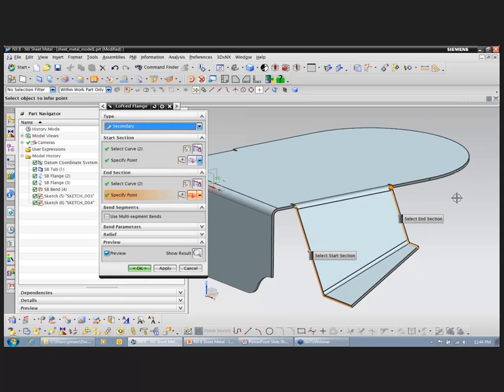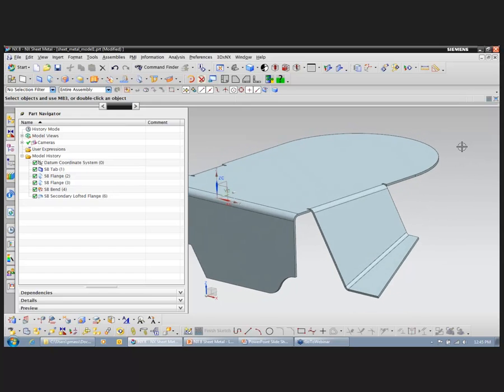In regular modeling space, this would take much more effort to produce a similar result. It's a powerful tool, this sheet metal application. I really like it. I wish it would have been around back when I was in configs design in the aerospace industry. That's what I did day in, day out, was create sheet metal brackets and tubing that run on the outside of a jet engine. We would have really killed to have a piece of software like this. I'm going to go ahead and select OK to create that flange.